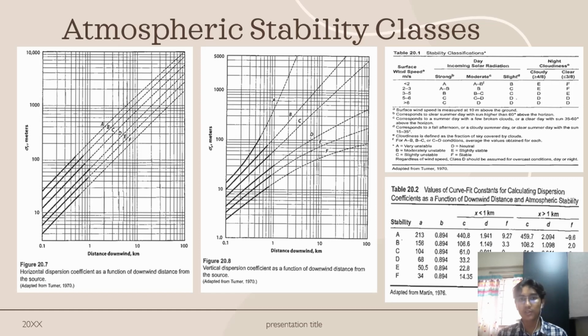The atmospheric stability class is a crucial element of the Gaussian model. Now, air is termed unstable when there is good vertical mixing. This occurs with strong insolation combined with light wind. As a result of absorbing solar energy, the Earth's surface heats and then warms the layers of air near the ground. The warm air rises, promoting vertical mixing. Stable air results when the surface of the Earth is cooler than the air above it. Then the layers of air next to the Earth are cooled and no vertical mixing can occur.